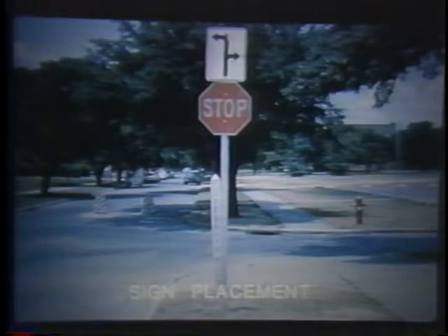Effective communication with drivers is the goal of all signs. In striving for effective communication, signs themselves should not become a driving hazard. The location of signs and the placement of signs are also important to their proper functioning. Signs should be placed where the sign supports will not become a hazard to vehicles and in such a position that the clear zone can be maintained.